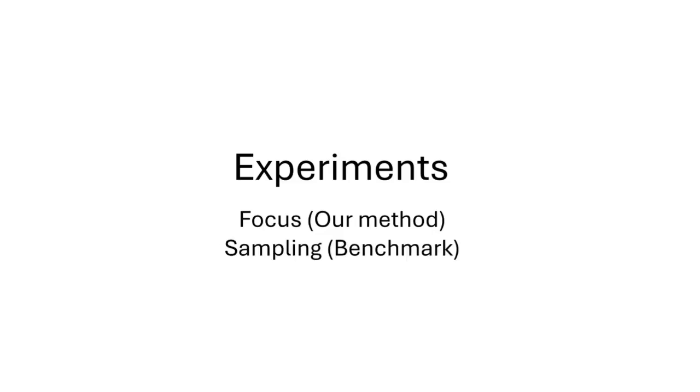We used the following three strategies while the robot moves between NBVs during the experiments. Focus: the robot keeps an informative focus point inside the camera field of view using our proposed method. Sampling: the robot uses an RRT star sampling-based method to plan an informative path. No path: the robot moves toward the NBV without focusing on any particular point.